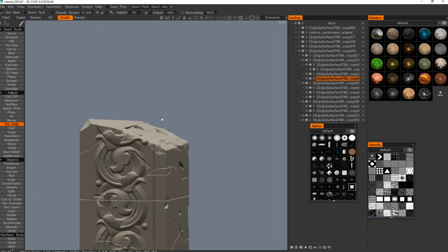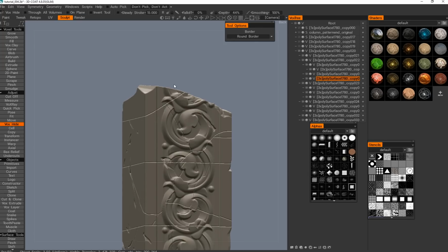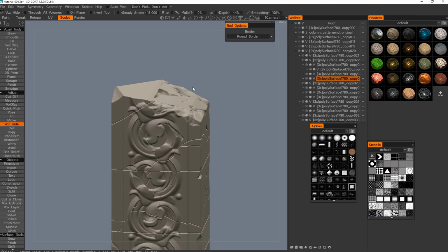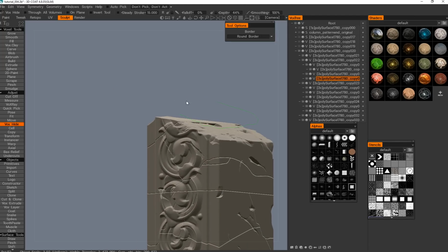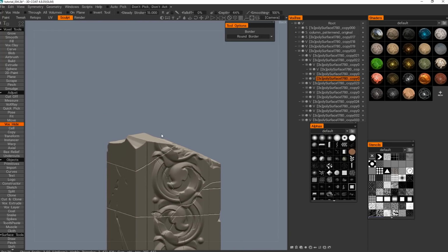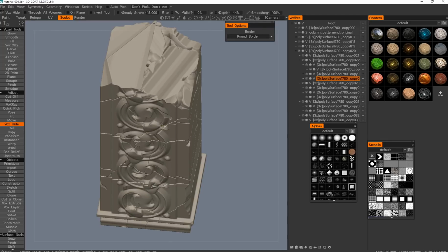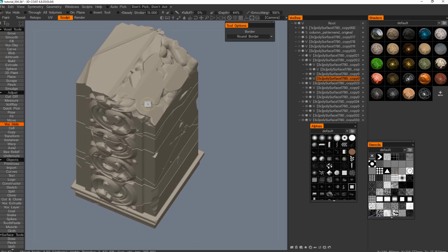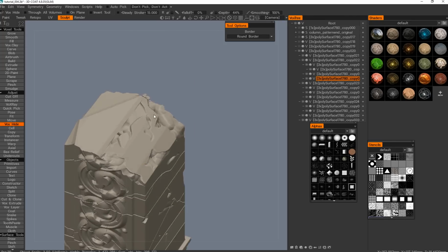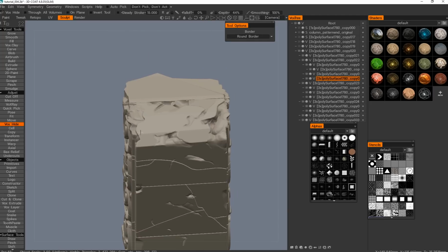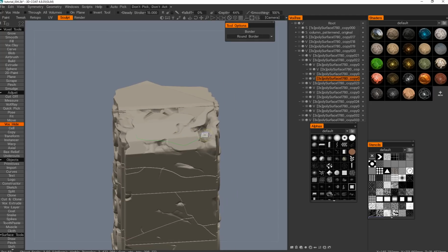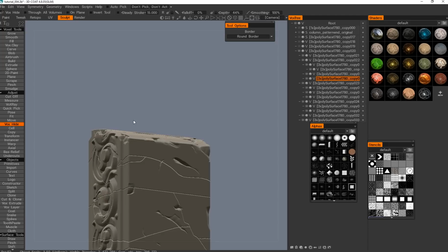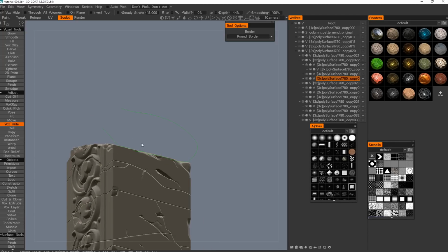And I'm really a big fan of voxel sculpting. You know, people will go into surface mode and try to do that, but I think it's much more physically correct to do it in voxel mode. And I'm not a fan of fake alphas, like in fake cracks, all that stuff. I've done it, of course, myself, but I think you can achieve a better result if you use voxel and actually deal with the actual volume that you have without trying to fake it too much. But I mean, everyone's got their own approach, and here I'm sharing my own.